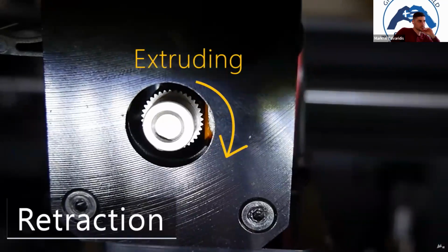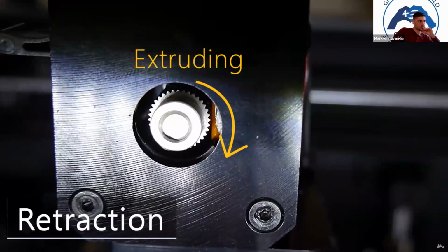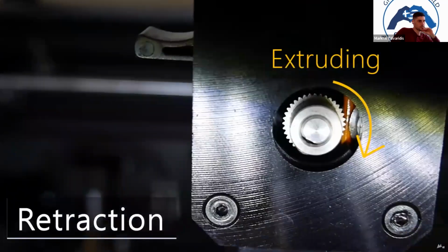Retraction actually pulls filament back up from the hot end a short amount after each print move. There's actually a bit of a myth around retraction that somehow creates a suction and sucks molten plastic back into the hot end, but that's not actually the case. All retraction is doing is relieving that pressure, so when you do a travel move, the plastic's not going to so easily ooze out. So let's turn on basic retraction.